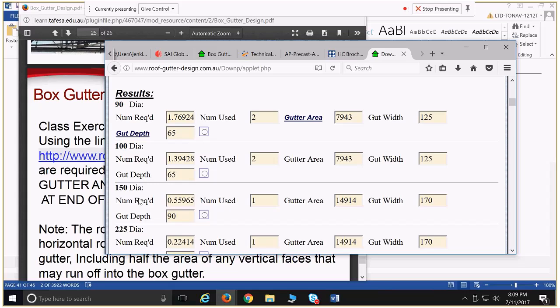So this is by far the most common scenario. You have two 90 millimeter downpipes there. It is very rare that you would deviate from that scenario for many reasons. One, because it's certainly less risky. It's also much more practical because you're dealing with smaller sections of downpipe, 90 millimeters instead of 150 millimeters, which is expensive, and smaller bits of gutter. And the aesthetic considerations are generally not too important there. Sometimes they are, and so you look for other scenarios.